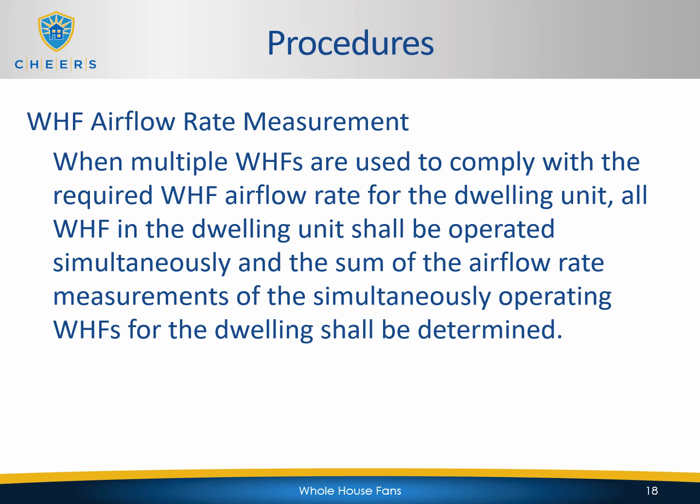So sometimes you'll have just a single whole house fan. It'll be a large one. It'll move all the air that you need for the dwelling because it's a small dwelling. But they also have other styles where they're smaller fans and they're made to be installed in different portions of the home so that you can have it running in one part of the house but not the other. And they don't move as much air, but there's still going to be a total target that you're going to need to hit. So when you do have multiples, you need to have all of them running and take that measurement. And depending on what equipment you're using will determine how exactly you do that, and we'll talk about that when we get into the actual procedure itself.